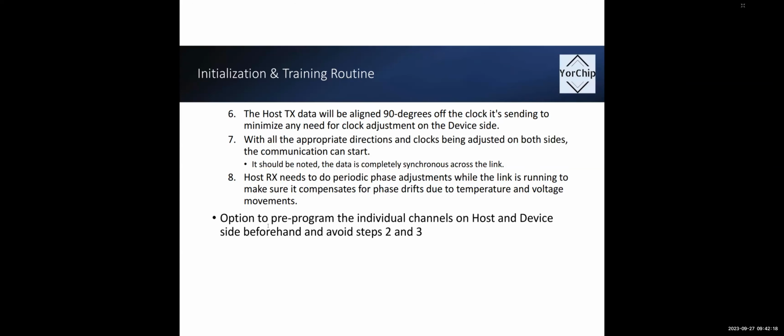You have to have the receiver tell the transmitter to do certain things, since the receiver is not doing the movement anymore. And from a very detailed architecture standpoint, one can show that the split point of the clock and the data is the thing that you care about, and this pushes that split point earlier than otherwise.